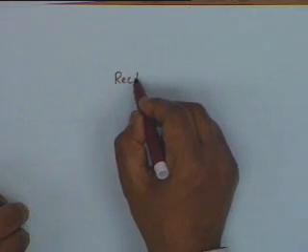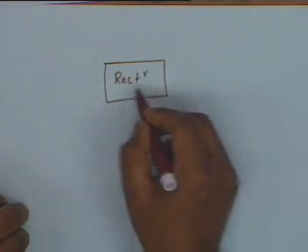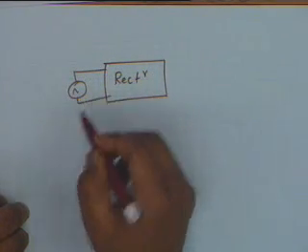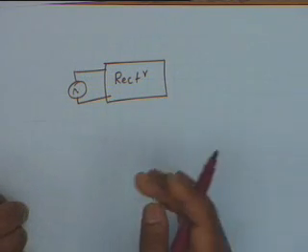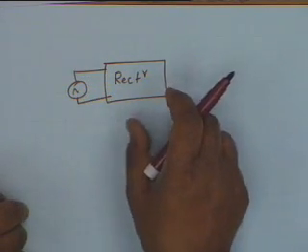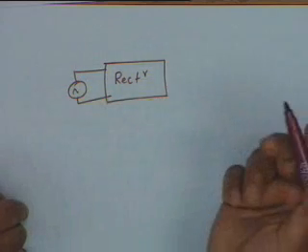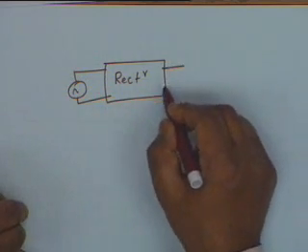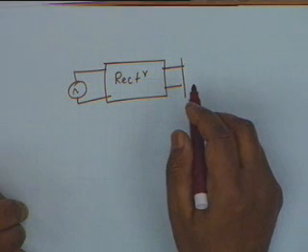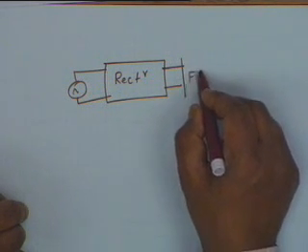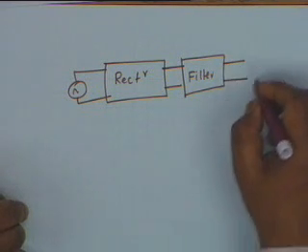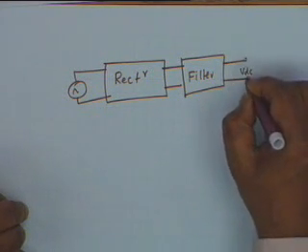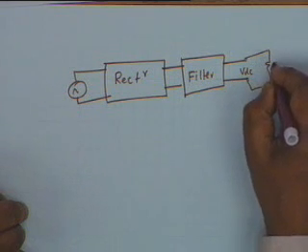Well, the motivation is this, that if you want a DC power supply, what you do is you take an AC, transform it step up or step down, subject it to rectification, half wave, full wave, bridge or the other type. Then, to kill the ripples, you use a filter, you smooth out, and the output should be pure DC. This is VDC, and then you apply it to the load, let us say RL.